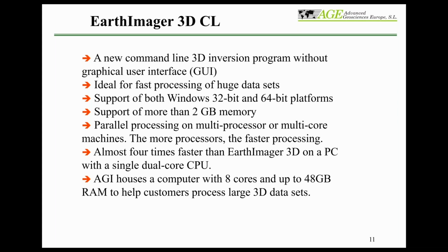So in that case, you need to use the EarthImager 3D command line version, which is a 64-bit platform. Then it doesn't have a graphic interface. It just runs on the platform with parallel processing, on multiprocessor machines, like almost everybody now has even in small laptops, and you can just run it.